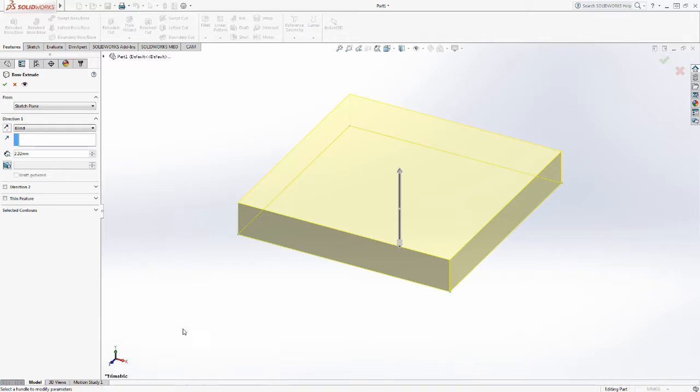But anyhow, this is going to be in the Z direction. So when we're actually in the CAM, it will be a Z direction. So this is 2.32 millimeters up from 0. We're selecting the direction as blind, in the up direction. We could reverse the direction so that the top of our part is 0, and all the values in the CAM would be negative then, so it would be going down to negative 2.32 if we were cutting anything through it.